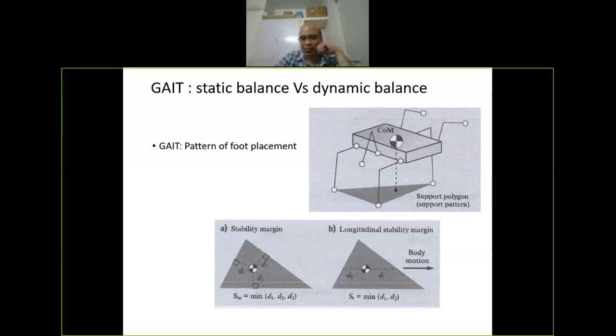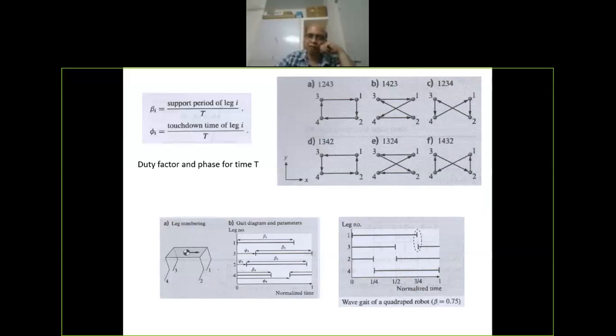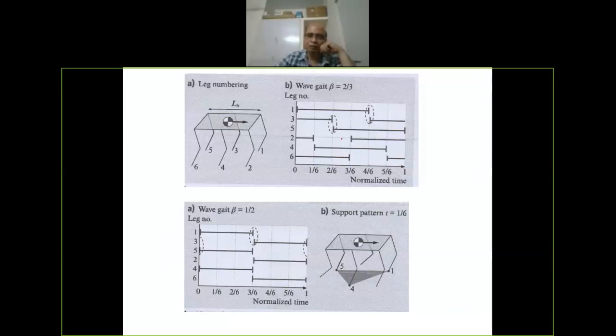Okay, as we go along we'll look at two-legged systems, and that is what we basically mean by a gait cycle. How do we draw it? It's drawn this way. The figure on the bottom right shows the robot having 6 legs, and the gait diagram on the bottom left shows the 1, 3, 5, 4, 6 gait. Whenever a leg is on the ground, we mark it by a black line. Starting off at time equal to 0, legs number 1, 5, and 4 are on the ground, and 3, 2, and 6 are in air. Then at half the time, all the legs are on the ground. Then again, the other legs which were in air are now on the ground, and the ones on the ground are in the air. And it keeps repeating this.